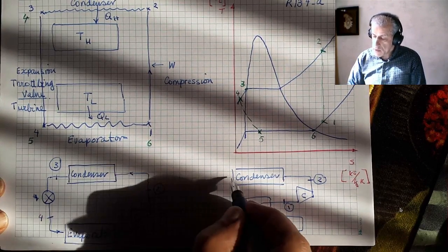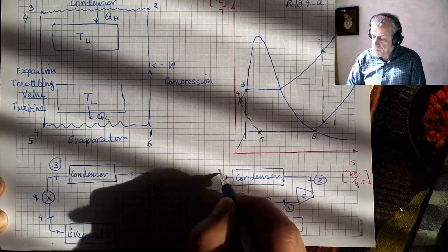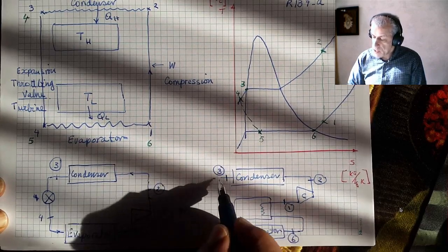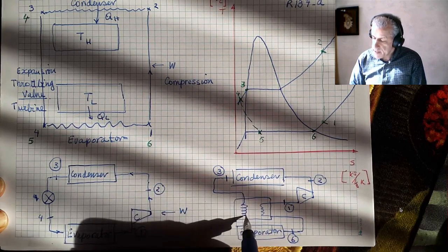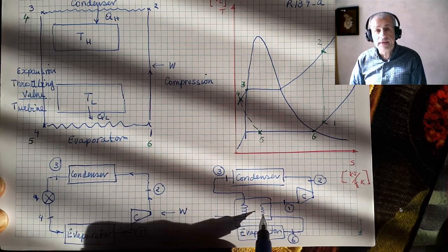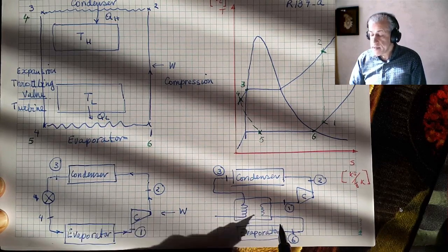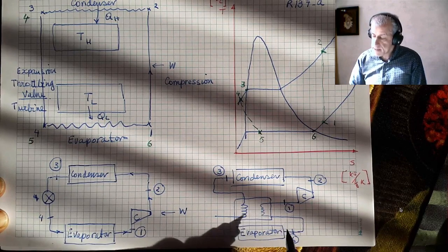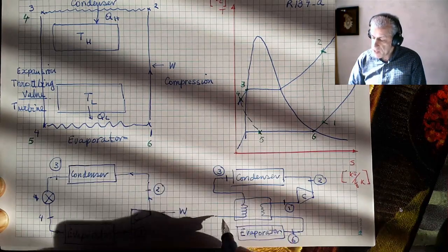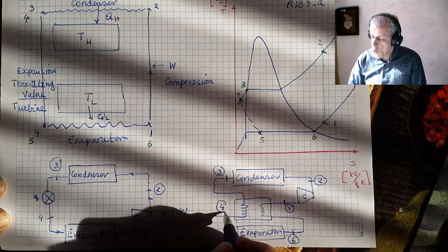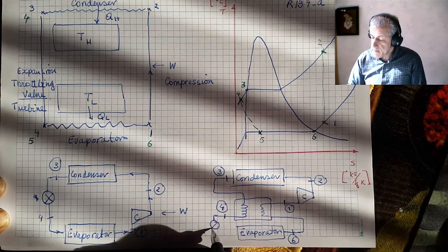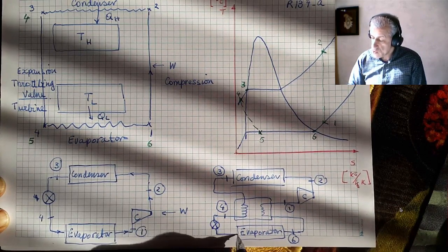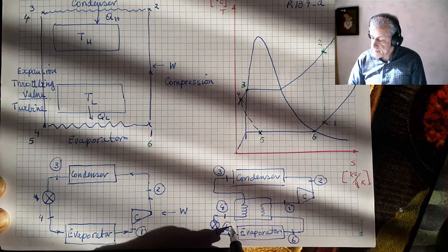And also, after the condenser at point 3, initially the fluid would go to the heat exchanger, would provide the heat that this evaporator exit medium requires, this one from 3, and then it is 4, and then it goes to the throttling valve, and then it goes to 6.